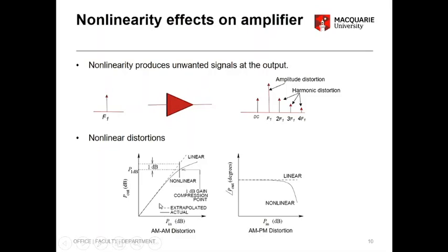These little things would be useful for you because in the exams there will be questions around this. So make sure if this axis is in dB. If this axis was not in dB, if it's voltage, out divided by in is your gain, voltage gain.